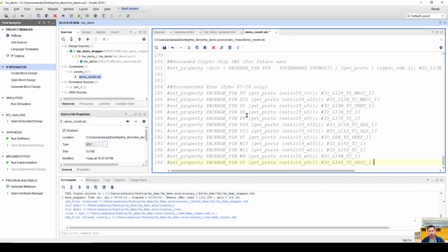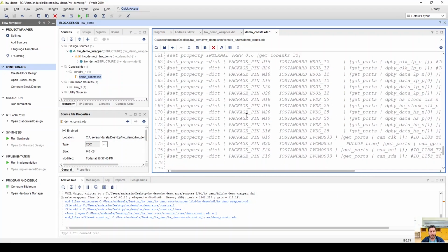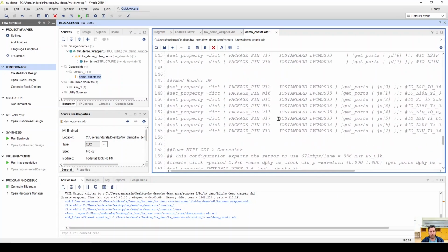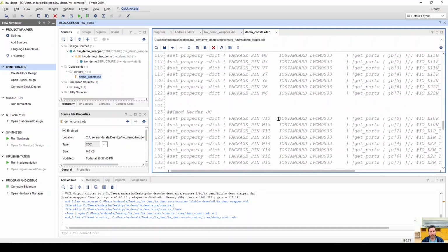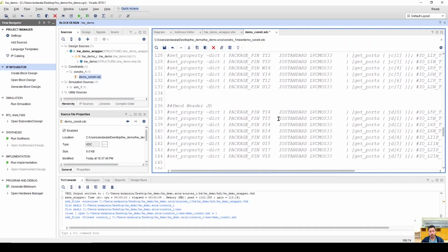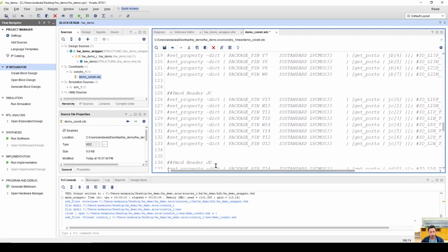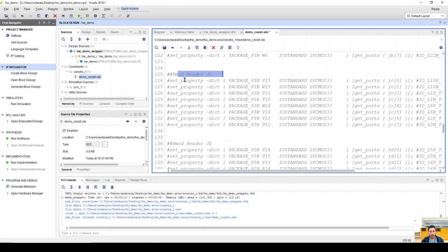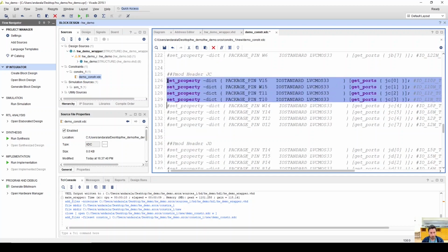The master constraint file is basically a commented file that has all the ports that are available on the board and that we can access. In this case, we are going to connect the SSD between the PMOD headers C and D, JC and JD. If you're familiar with Vivado hardware development, you'll recognize this. If not, then not so much.